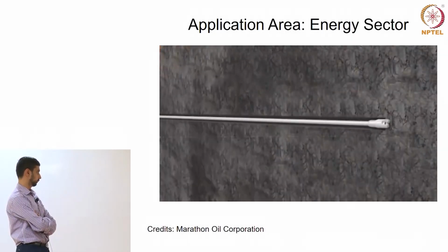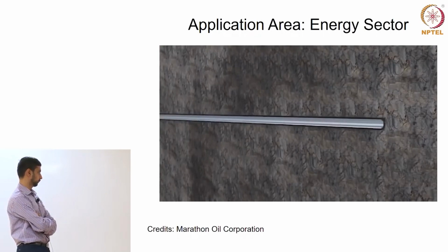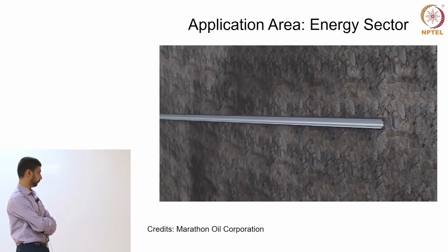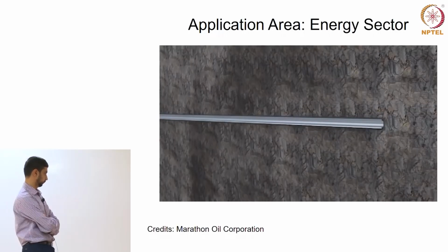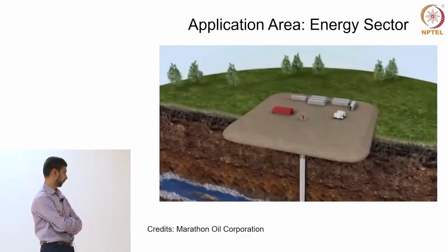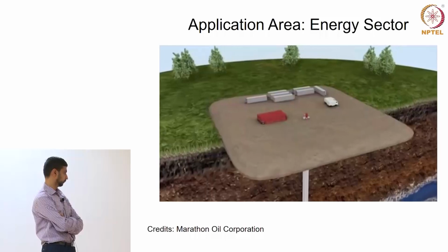When the targeted distance is reached, the drill pipe is removed, and additional steel casing is inserted through the full length of the wellbore. Once again, the casing is cemented in place. For some horizontal developments, new technology in the form of sliding sleeves and mechanical isolation devices replaces cement in the creation of isolations along the wellbore. Once the drilling is finished and the final casing has been installed, the drilling rig is removed and preparations are made for the next steps.